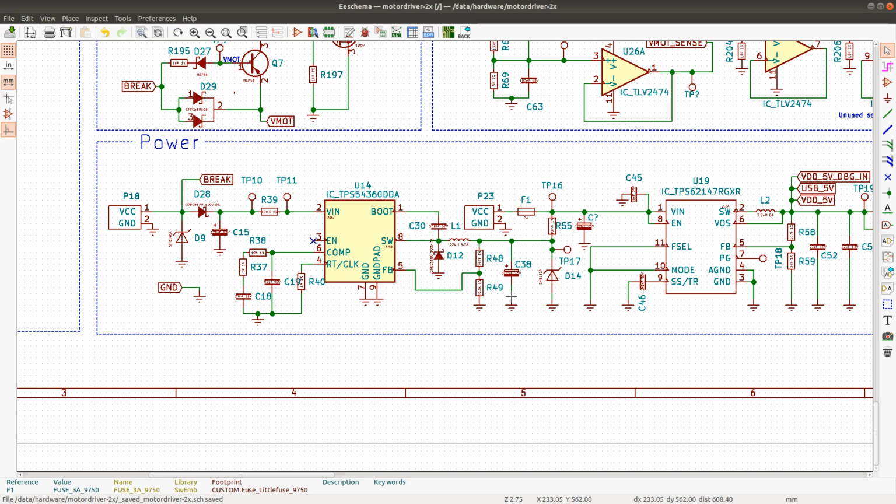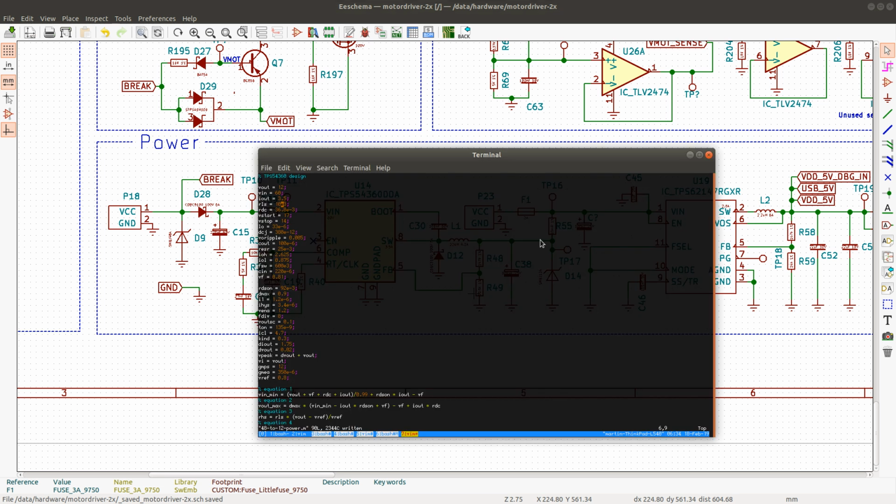The calculations from the designer tool used a 10.5K resistor there and then a 147K resistor there, and this gives exact division. Now, if I use a 10K resistor, I may get an inexact division here, so I may not get a precise output voltage. So maybe it's good to use the 10.5K resistor anyway. But first I'll go over the parameters. I can update this to 10K and see what result it gives me.